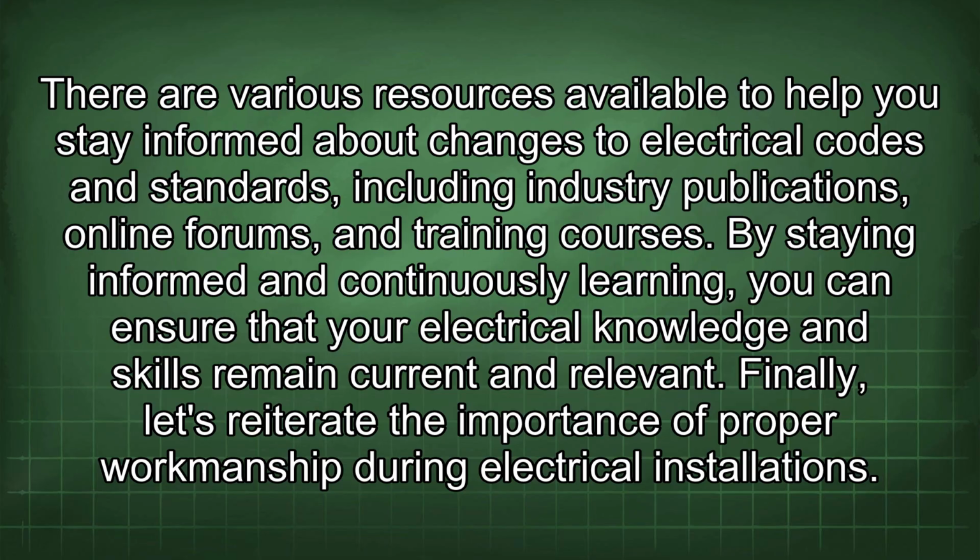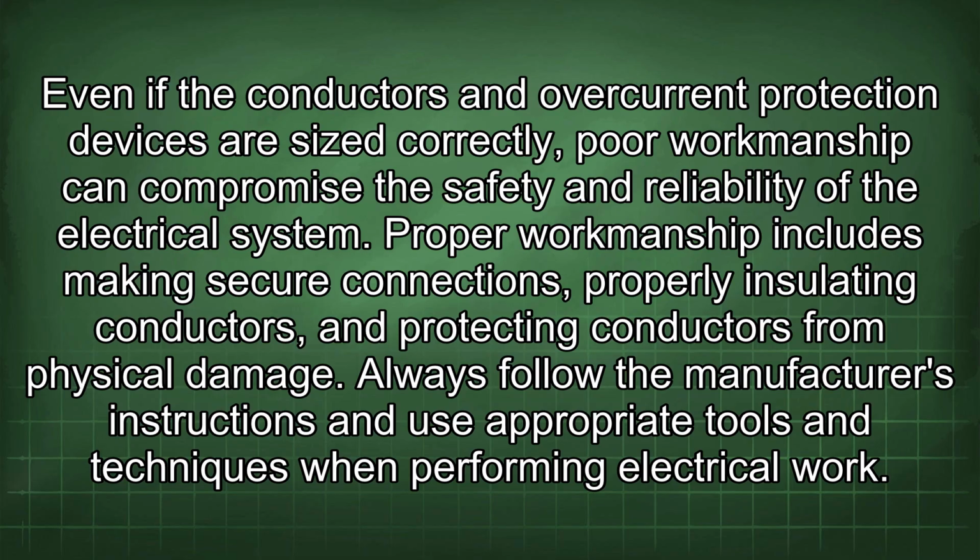Finally, let's reiterate the importance of proper workmanship during electrical installations. Even if the conductors and overcurrent protection devices are sized correctly, poor workmanship can compromise the safety and reliability of the electrical system. Proper workmanship includes making secure connections, properly insulating conductors, and protecting conductors from physical damage.